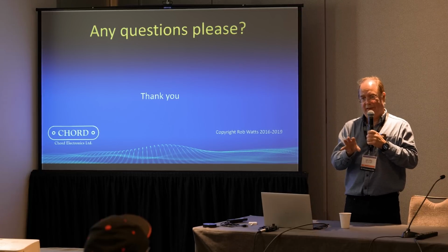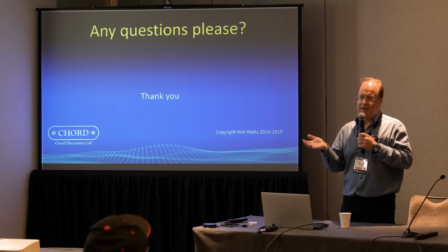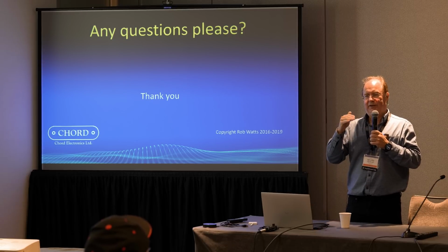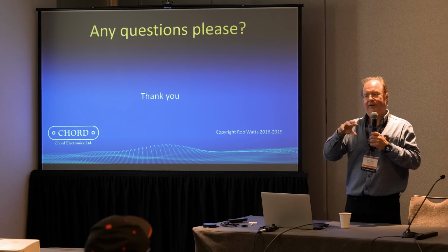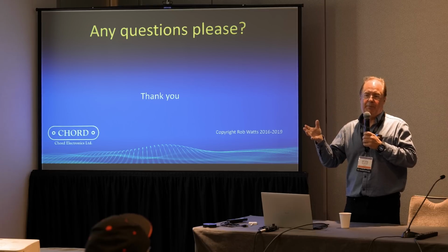So you want to remove that. By removing that, you're filtering. By filtering, you're converting it into PCM. So there's never an argument for keeping DSD and running it as a DSD-only DAC. It's better to filter it correctly and then use it as regular PCM.